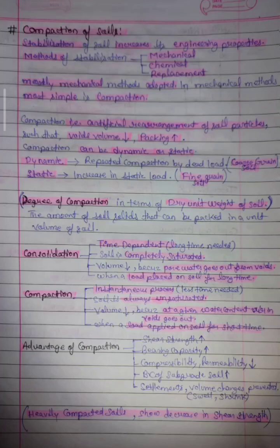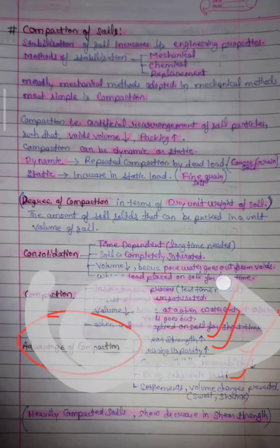Now advantages of compaction. The shear strength will increase, bearing capacity of soil will increase, compressibility and permeability of soil will decrease, bearing capacity of subgrade soil will increase, settlements and volume changes are prevented, swell and shrink are also prevented. So these are all the advantages of compaction.